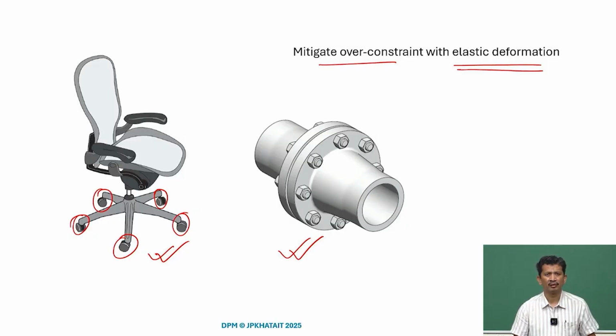Here the main purpose of using bolts is to create that joint, and sometimes we use it to even locate, but as we know, location using bolts may not be a good idea because the clearances are there, and we have to use some kind of jigs and fixturing to get a proper alignment.